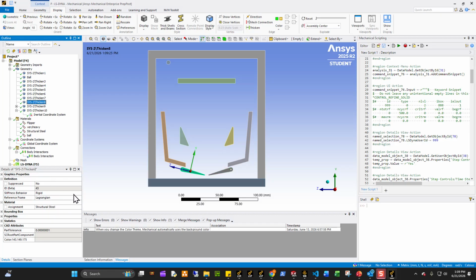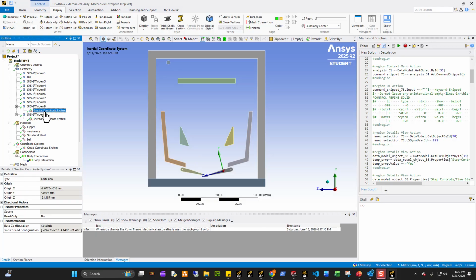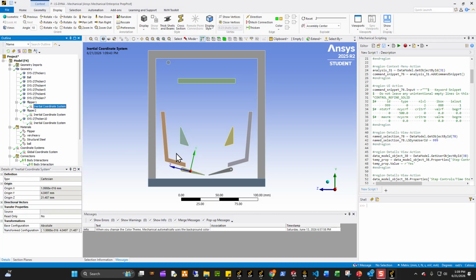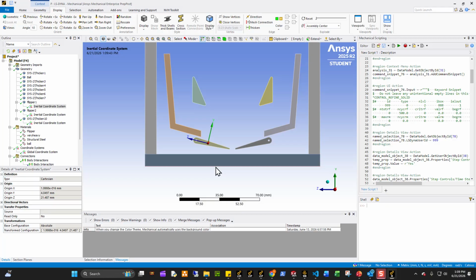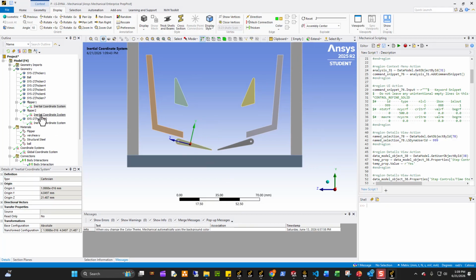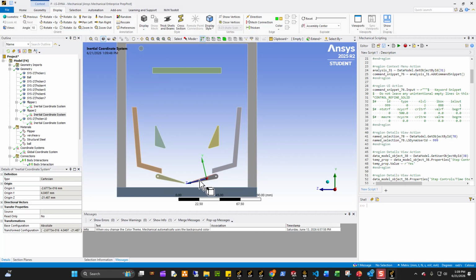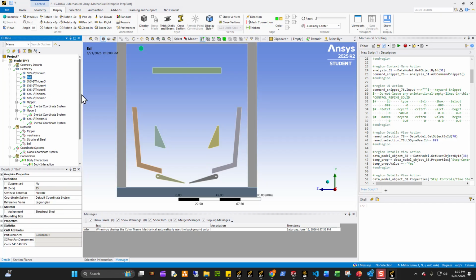It doesn't actually show the coordinate system. But one thing that you want to see is that this is flipper 2, and this is flipper 1. And what I like to show about these flippers, right, is that if you take a look at the inertial coordinate system that's created by Workbench, that is actually the rotation joint that we're generating. Because when we generate a boundary prescribed motion rotation for one of the rigid bodies, by default it's going to rotate relative to the centroid, the CG. And that's the one thing we wanted to do.